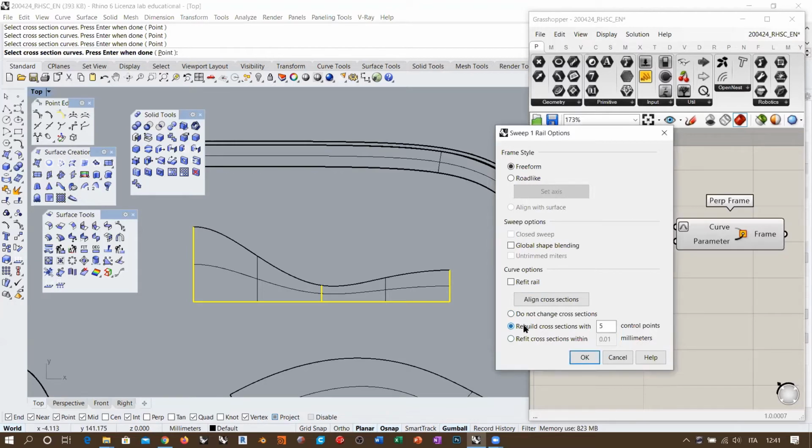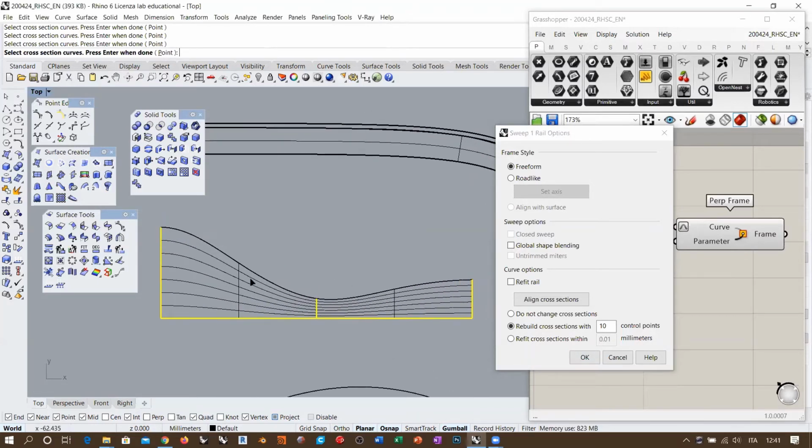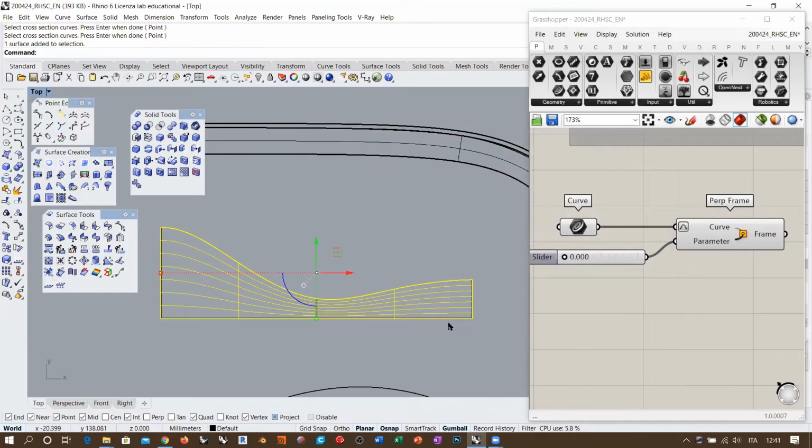Okay, so if you rebuild them, you will always have, well, 5 control points produce 1 single internal knot, so there is always the same longitudinal isocurve, but it becomes a real isocurve and not a visual one. But if you take more control points, you will have more longitudinal isocurves. Remember, you do this only if you need it. Okay, it's not because having all these lines visible is nice visually, but if you don't need it, don't do it.